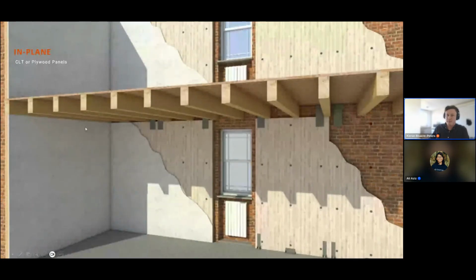As an alternative to in-plane shear strengthening with concrete shear walls, CLT or plywood overlays are also a good option. This technique has been used in New Zealand, Canada, and the United States so far that I'm aware of personally. And there's a significant amount of design and test data and reports out there. It comes down to the hold down connections. But definitely something that is a good option if you need a more low profile, reversible retrofit solution for in-plane shear strengthening.